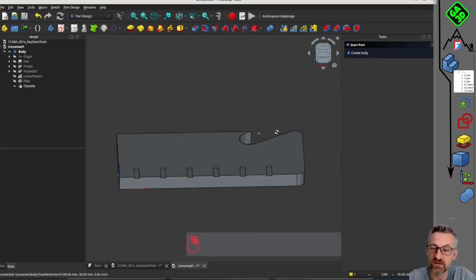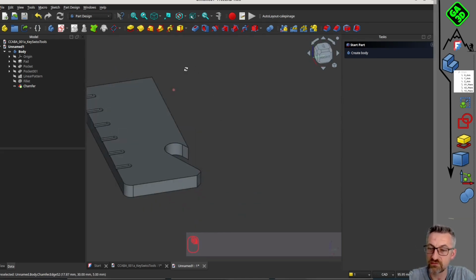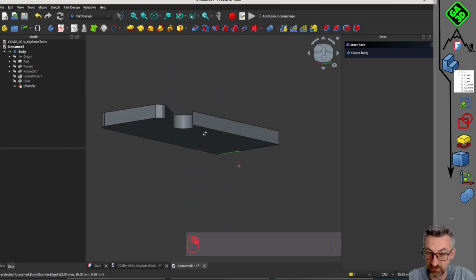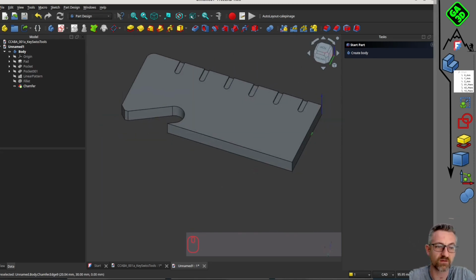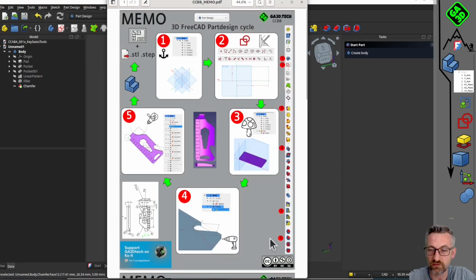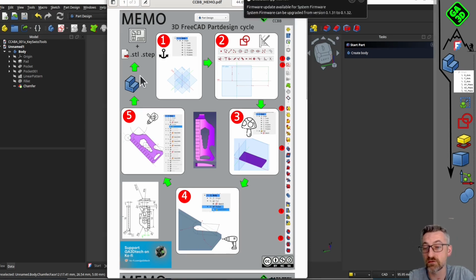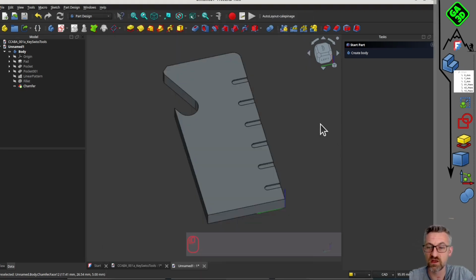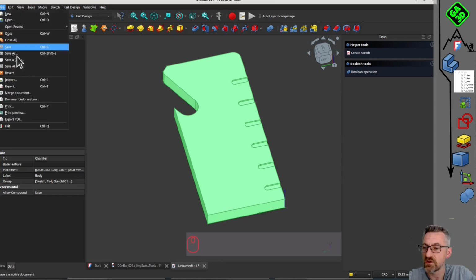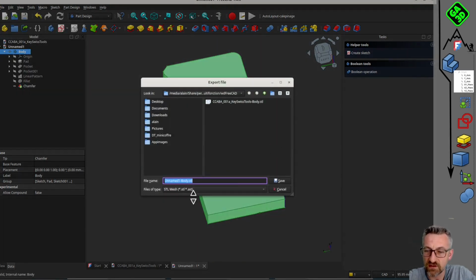If you do it quickly in the construction tree, there must be a good reason, otherwise generally, we do all the volume creation operations and material removal. And we put the chamfers and radii at the end to facilitate the calculation, because behind all this, there are still quite a few calculations, and it quickly becomes complex. So we finished our first cycle of modeling creation.